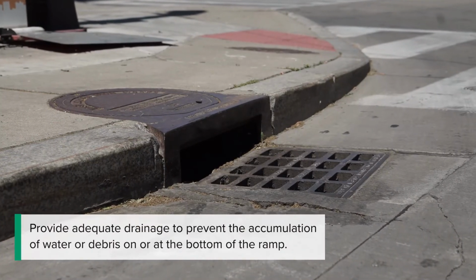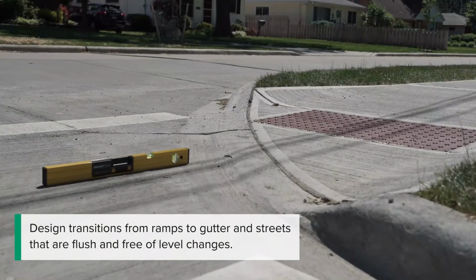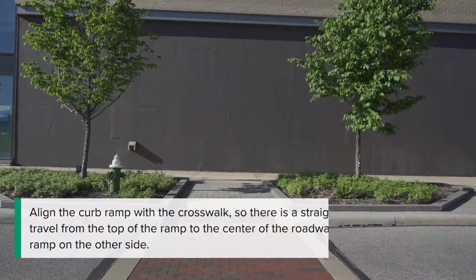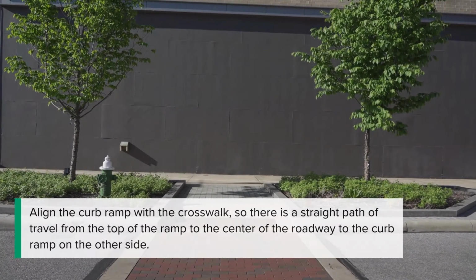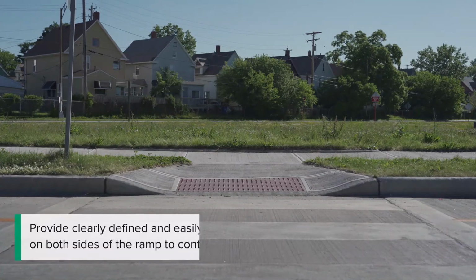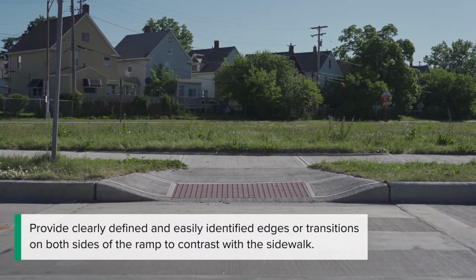Provide adequate drainage to prevent the accumulation of water or debris on or at the bottom of the ramp. Design transitions from ramps to gutter and streets that are flush and free of level changes. Align the curb ramp with the crosswalk so there is a straight path of travel from the top of the ramp to the center of the roadway to the curb ramp on the other side. Provide clearly defined and easily identified edges or transitions on both sides of the ramp to contrast with the sidewalk.